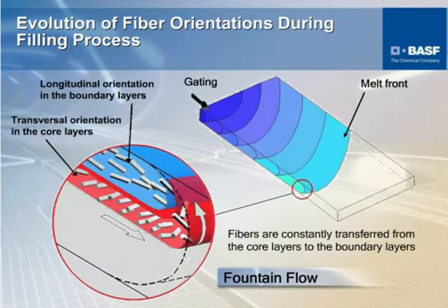All right, and this is showing it in a little more detail. If you're injecting the plastic, what we call the gating, and you gate it here at this end, it's going to give you a certain filling pattern. And this would be, if you looked at a short shot, if you stop your mold at every 1/10 of a second or so, you would see the part filling out just like this. And again, on the outer section, the fibers are actually going to line up with the flow. They're going to line up this way. Right in the center of the part, you can see the fibers are actually going to line up transverse to flow.